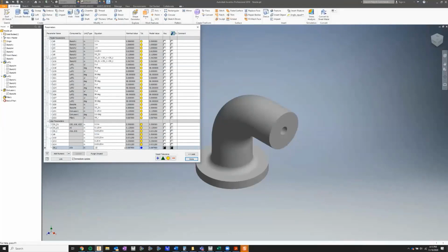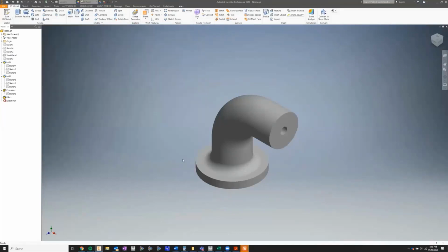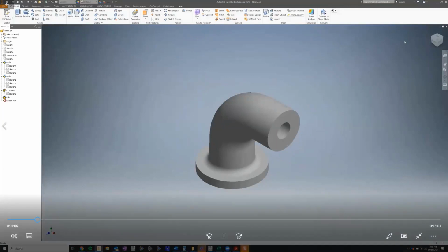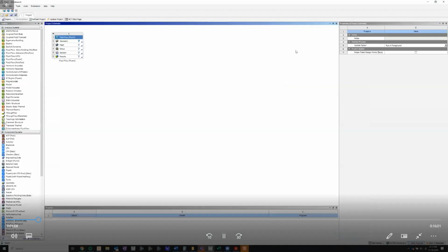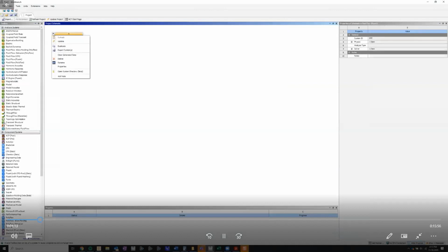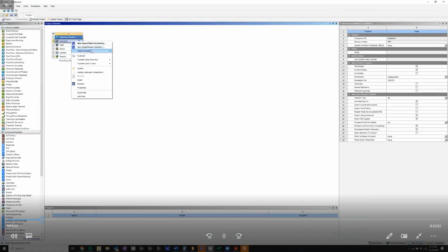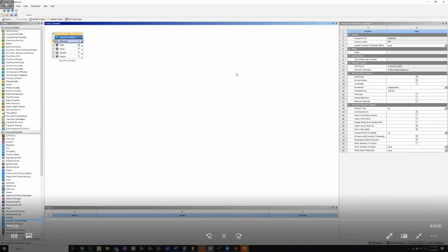But if you're using SolidWorks or any other tool, you could directly import the geometry parameters from that CAD tool into Ansys Workbench. And what happens is when it comes over to your prep tool, for example, if you import it inside SpaceClaim, you should automatically be able to see those constraints.